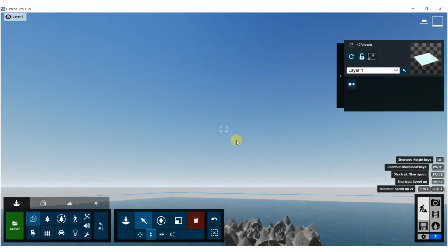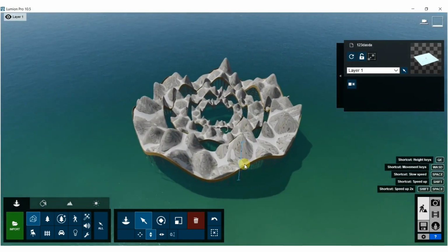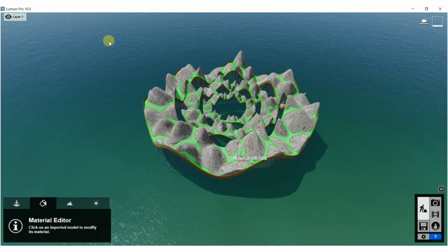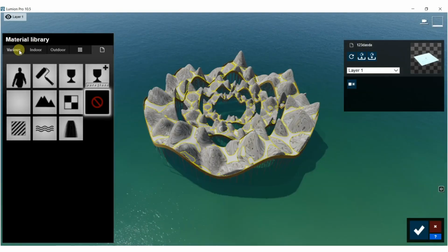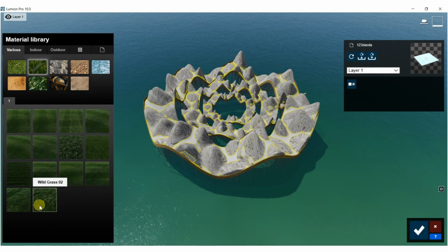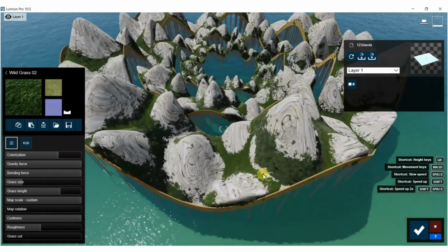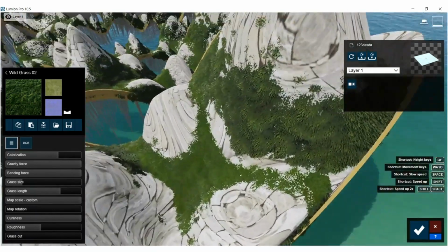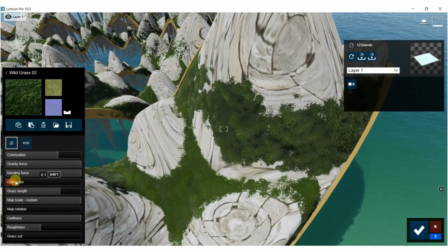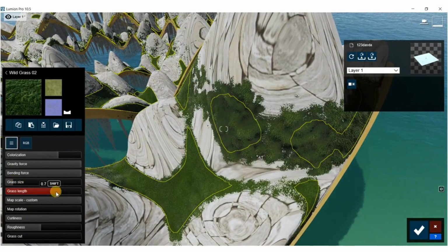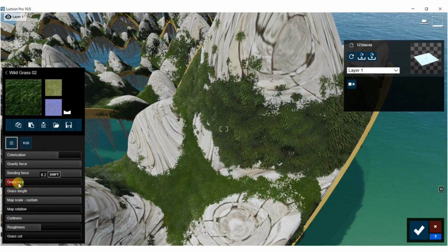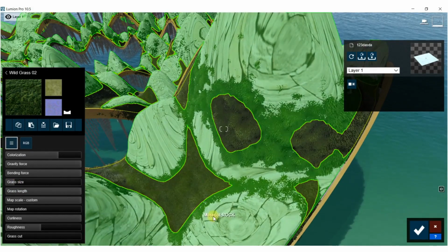All right, so we're all in Lumion, and it imported really quick because it's a light model. So let's start adding materials out. So this would be the grass, like we discussed earlier. Do 3D grass. Let that kind of puncture through. That's looking great. So even parts that really start to stick out of the model, I think that's awesome. We're going to turn down the actual size of the grass. We can make it long. Size, we could leave it around there.